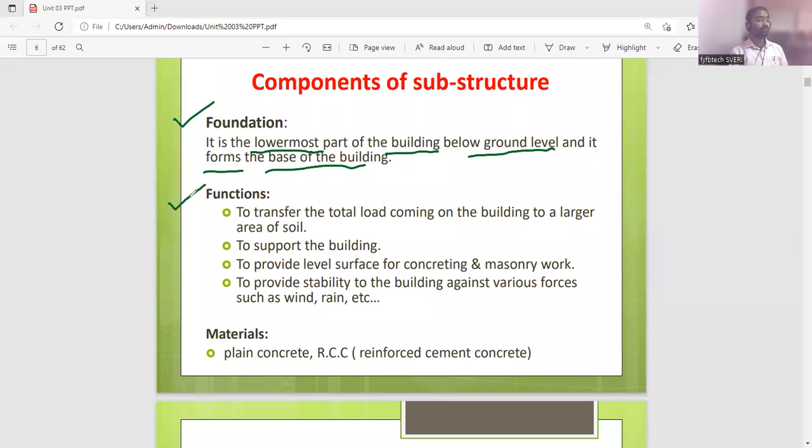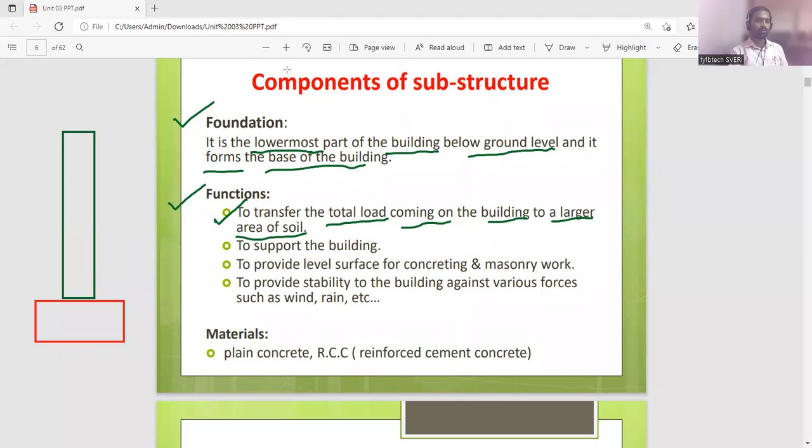Okay, sir. What is the function of this foundation? Why we have to take the foundation? इसका function क्या है? First one, it transfers the total load coming on the building to a larger area of the soil. Yes. So you have seen this is the entire wall, or you can take column. There is a foundation for this one. So what this wall or column will do, it will take the entire load and it will transfer to the foundation. So what this foundation will do, all this entire load will take and it will spread to the soil.